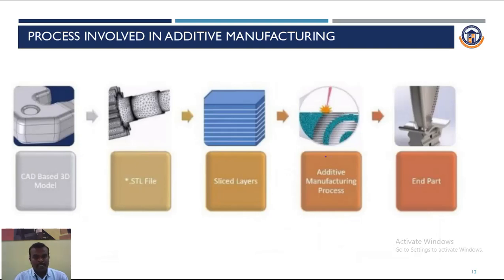So in slicing software we have to slice based on that design, and the infill ratio, orientation, support layers, lighting, all these things will be considered. We slice the given model into a number of layers. The output of the slicing software is G codes. The G codes are fed directly into the machines. The machine language is only G codes and miscellaneous codes.